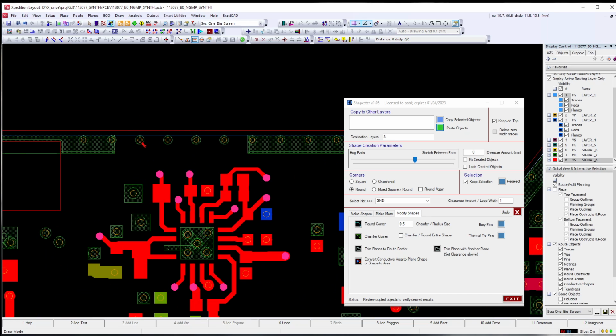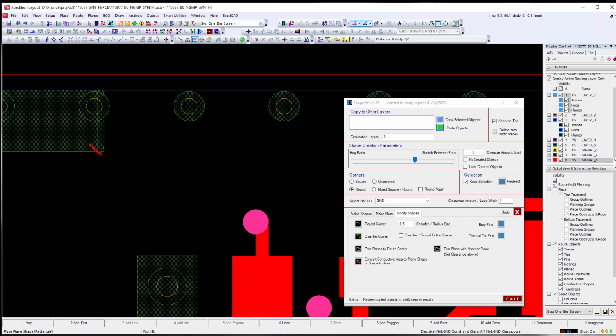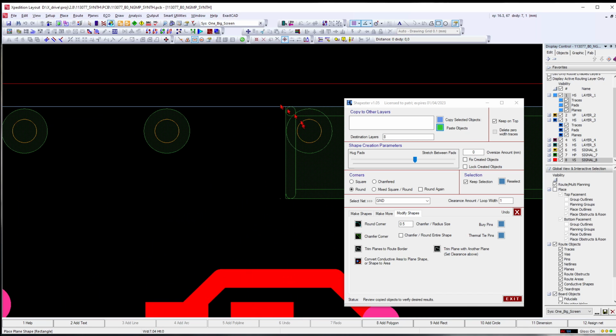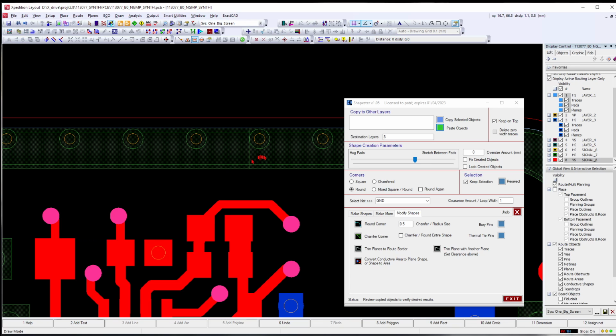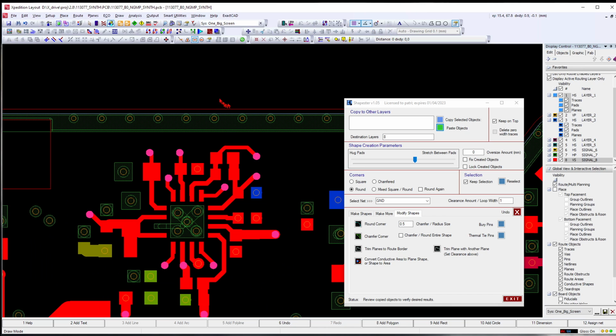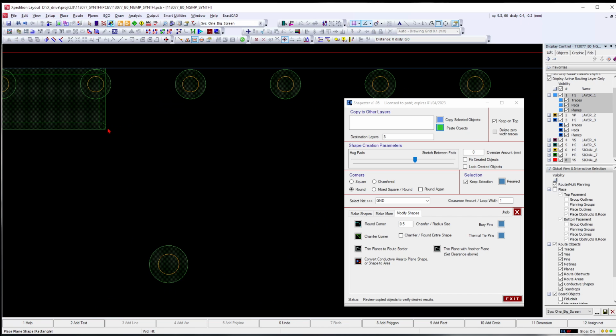So now the only thing to do is to put this back together. A real easy way to do that is just to draw a rectangle and set the snap mode on. Go from there to there, and then just grab this and that, hit the combine button right here, and same thing on the top. And I could have done this before copying it to the bottom, would have worked just as well.